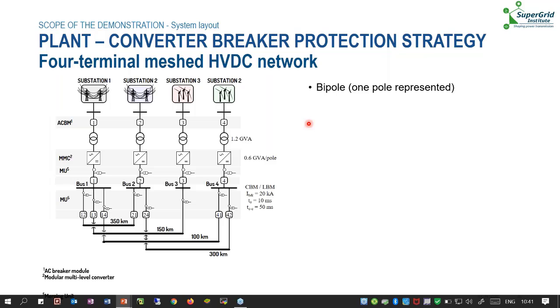Voltage and currents at the output of the MMC converter are needed. This is mainly to allow the supervision system to understand the state of the converter. And downstream, you find the mechanical DC circuit breaker that protects the converter. The line breakers here, you have one per line end. And these arrows here indicate the communication needed for each one of these elements. So we implemented the IEC 61850 communication protocol for this purpose.